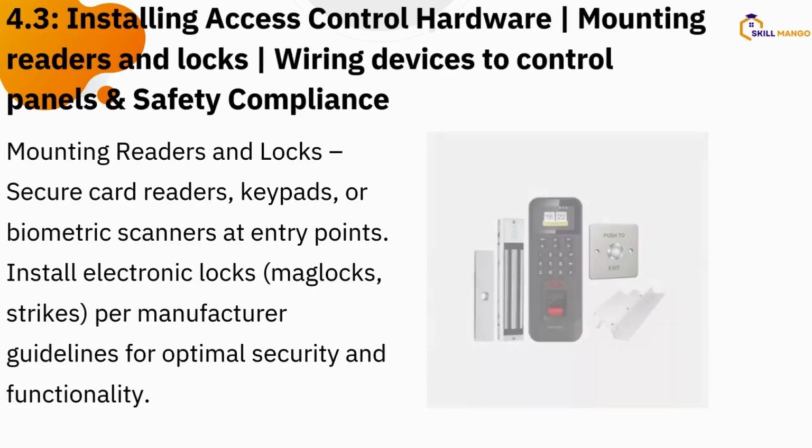So inside is the exit button. At the top is the magnetic lock. So the ideal thing to do is to mount your reader outside. Then you can drill into the wall, so the wire connectivity will go inside, and inside you can put your exit button at that spot where you're drilling, or you move it to a side where it can be easy for one to press it. Okay, so the wiring for the connectivity is not showing, it's inside the wall. You see if everything is there, fit.